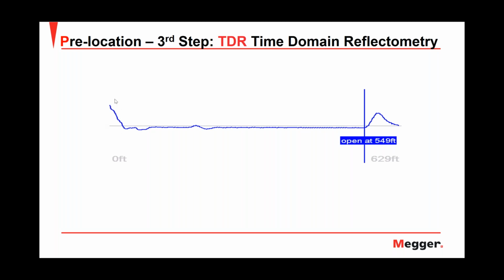This is the change of impedance that we have at the beginning of the trace. The second change of impedance that we can see very clearly is the end, in this case, the end of the cable. But if I have, let's say, a pinhole fault, it will not be possible to see that fault with the low voltage trace. So what I need to use is the arc reflection method, and that is the next method I would like to talk about, the arc reflection method.